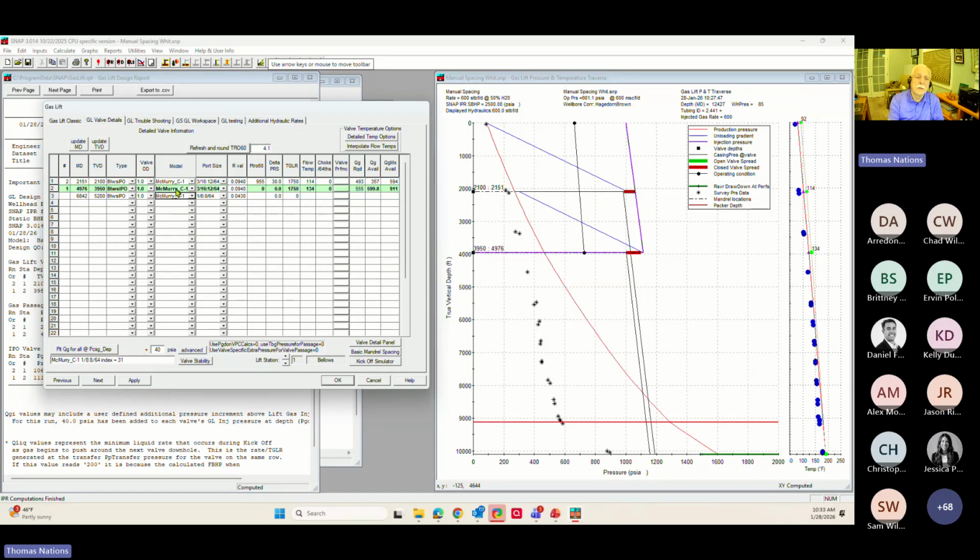So when I make that selection, and then make a port size selection, in the catalog, it also knows what that R value is. R value is the ratio of the area of the port divided by area of the bellows. And this is the thing that dates back to, well, why is it R? Well, Dr. Kermit Brown, who was the